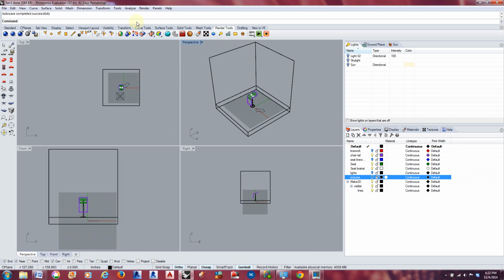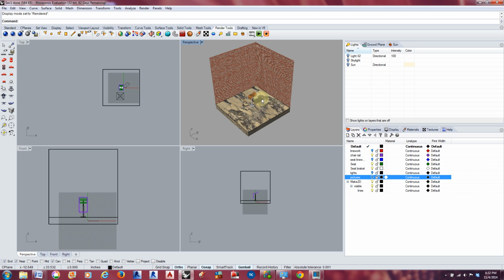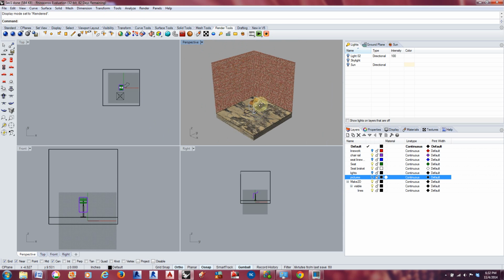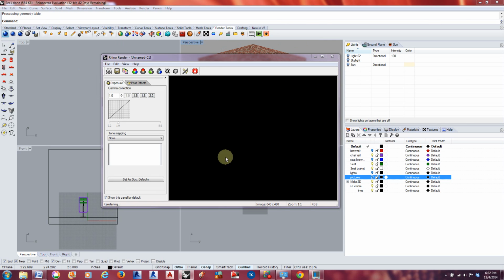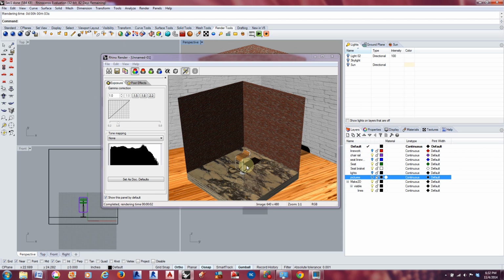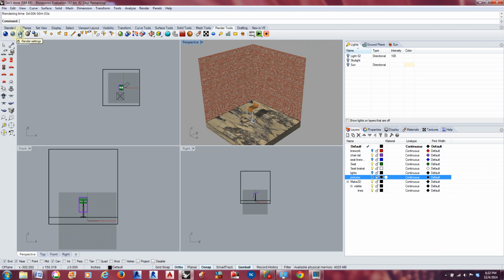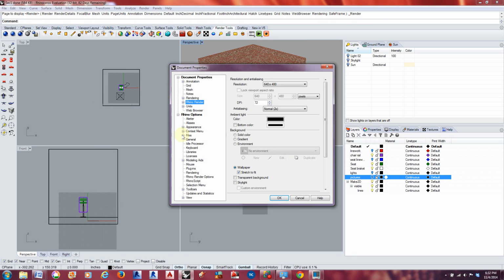Resume the video here. Because if I wanted to manipulate the image in Photoshop. Yeah, so the rendered view is just showing the materials realistically, but when you actually click on the render itself, it goes to a new dialog box where it actually renders the settings out. So where you start to change that is in the render settings. We can change our DPI to 300 pixels per inch, and we can change our resolution size.